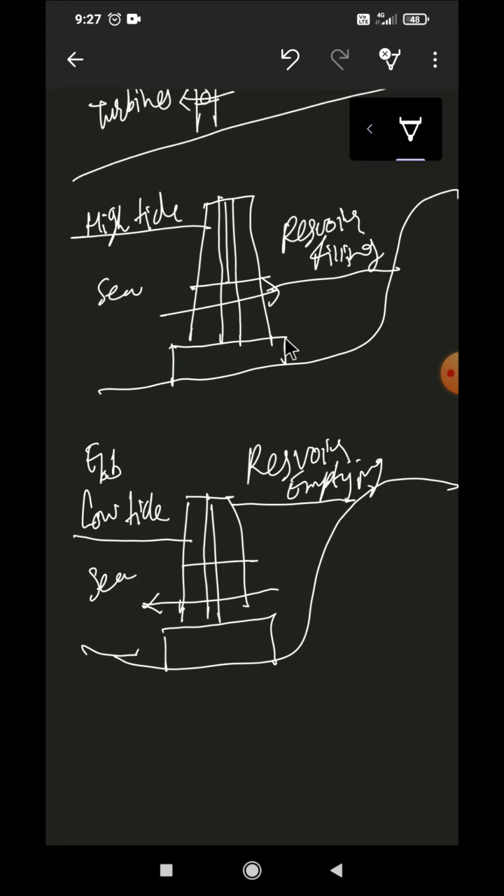of seawater. So turbines keep working until the rising level of the next flood tide and the falling reservoir level together reduce the effective head on a turbine to the extent where it can no longer work safely and efficiently. The turbines are then closed and the sluice gate opened again to repeat the cycle of operation. So this is how the tidal power generation works.